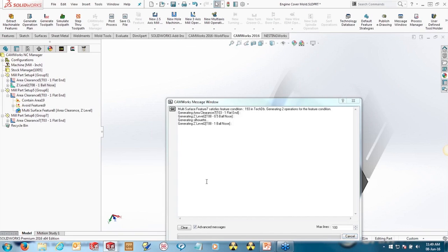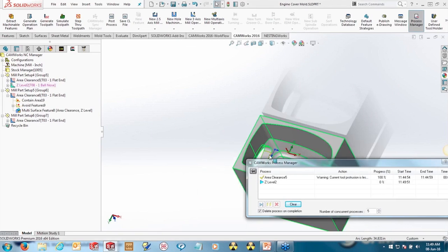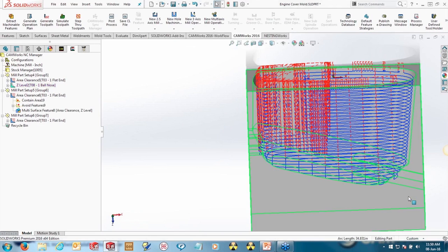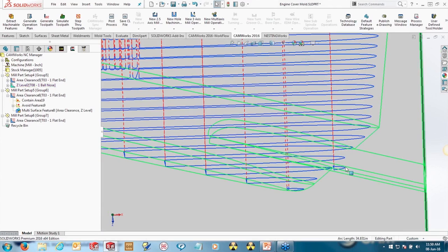You'll see it's going to basically hit those flats in here. So, which is not really desirable. Maybe those being machined from a separate direction. It's going to go in and start putting toolpath on those areas down here and just treating them straight down, which is not really great.